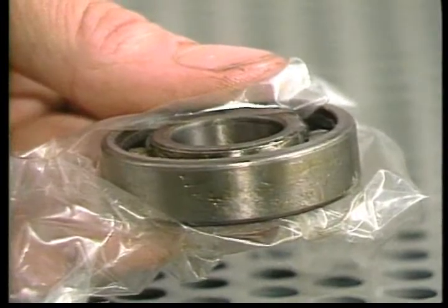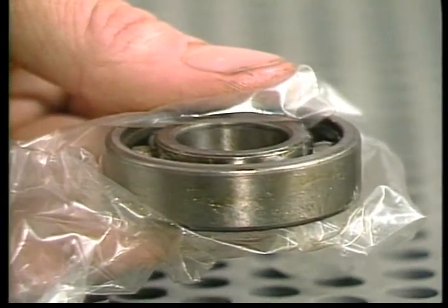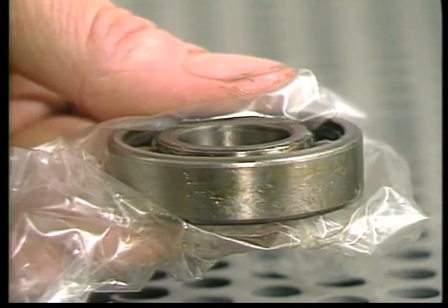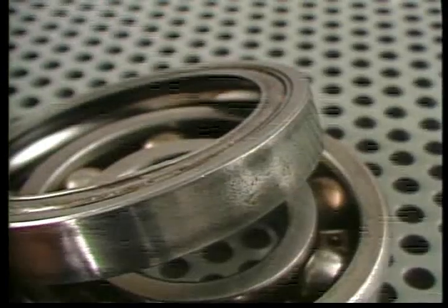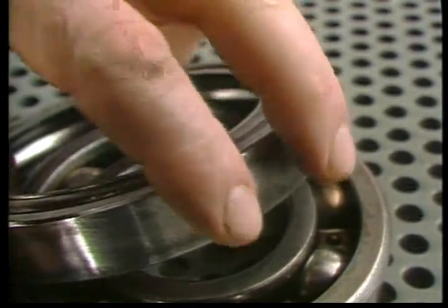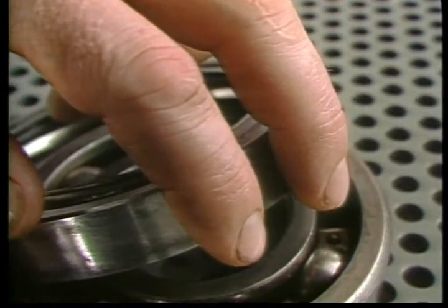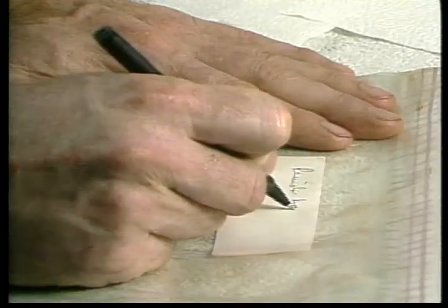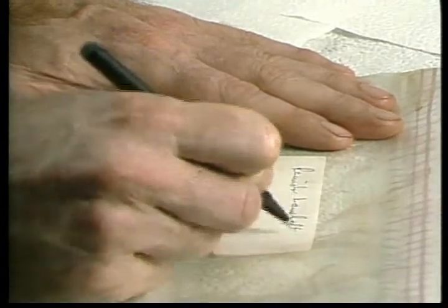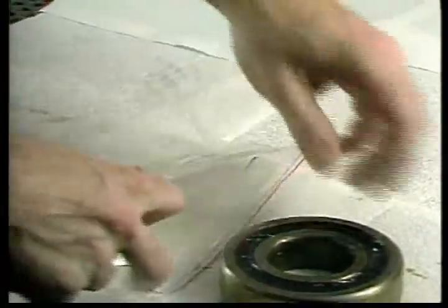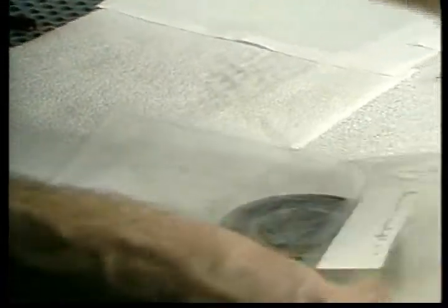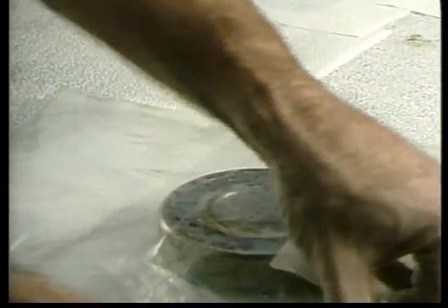They are coated with a protective film to prevent rust and corrosion. Do not remove this coating or store bearings dry, that is, without the protective film. Bearings rust easily. Since perspiration and skin oils are usually acids, even fingerprints can corrode a bearing. If a bearing is removed from equipment and stored for any length of time, pack it full of grease and seal it in a plastic bag with a label. This prevents air and moisture from coming into contact with the bearing metal.